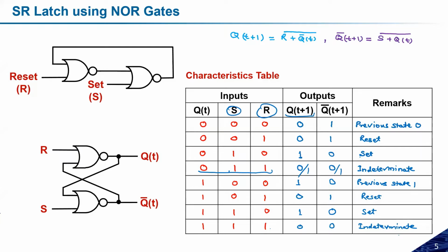In conclusion, we can say that at this stage, 011, these are don't care conditions. Similarly, the same applies to this case, 111. Here again we have an intermediate state, so we call them don't care states. Considering the don't care for these two cases, let us fill the K-map.